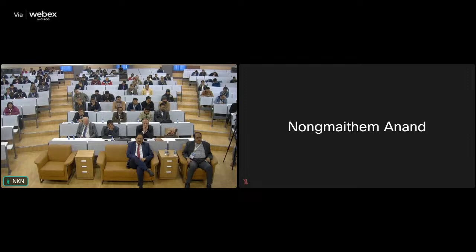And to conclude my talk, pre-grouting of the rock mass has been found to be effective in improving the rock mass quality. Now you can understand why I have mentioned this. Similarly, it is found that full column grouted untensioned rock bolts, I'm emphasizing untensioned because when you are tensioning the bolt, the cracks will be closed, help in improving the rock mass quality in case of poor to good rocks represented by Q between 1 and 40. The improvement in Q value is suggested to get modified rock mass quality. The improvement in Q is found to be more in poor rocks and less in good rocks.